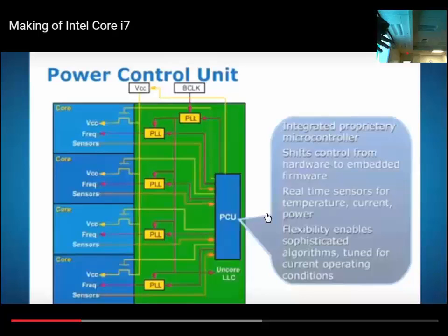So we said here that we have power that's dissipated by the chip. Power equates to cooling need. If you have power headroom, it means the chip is not overheated yet. You can make it a little bit hotter before it breaks. So what they're going to do here is change the frequency. When it starts to get too hot, they slow it down, it then cools down, then you have power headroom, you've made some space, and you can jack the frequency back up, or the voltage.